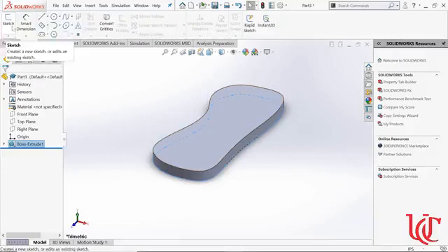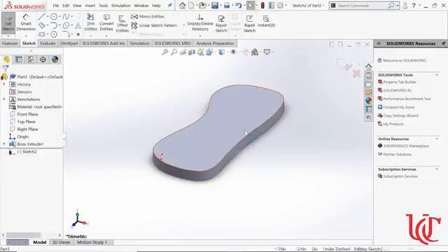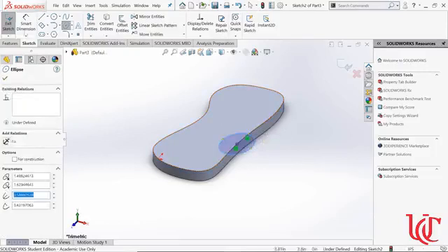So to sketch now, it's going to be a different 3D feature because I can't use boss extrude or extend linearly. I need to make a new sketch. So I'm going to sketch. Now on this plane or this top surface, instead of my bottom plane, I can select it just like any other plane and start sketching here. I'm going to start sketching with an ellipse that starts on this edge and goes some distance and over.